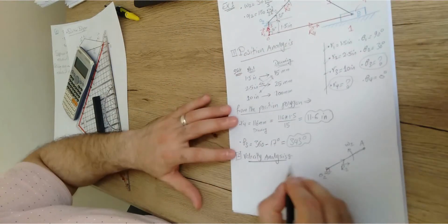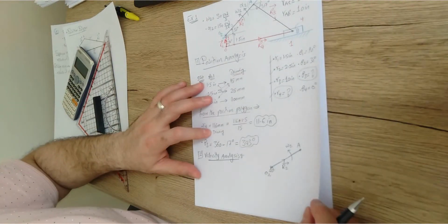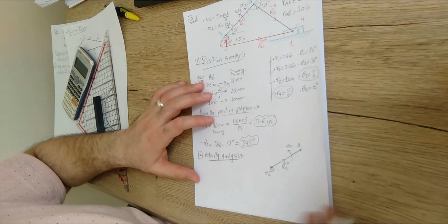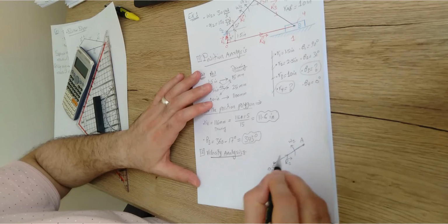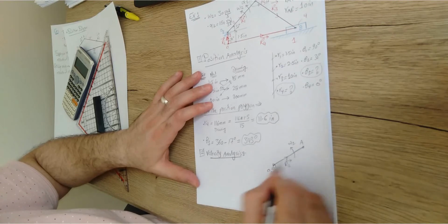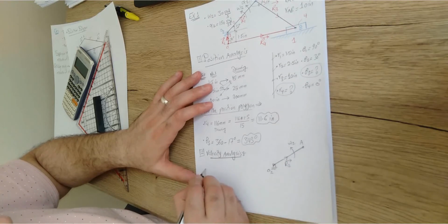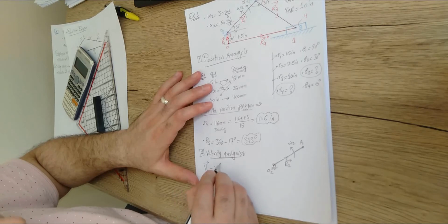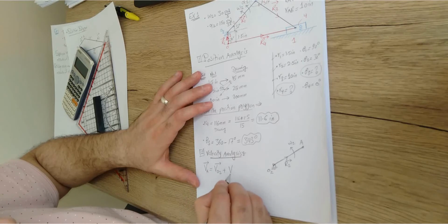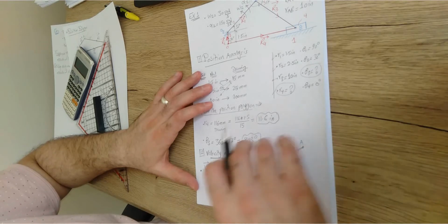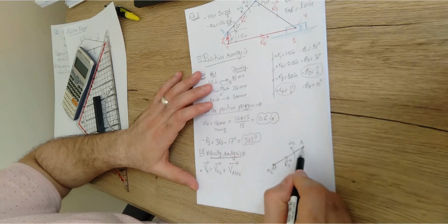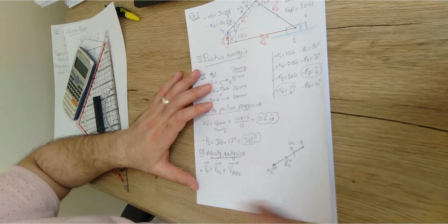Then your objective is to start writing the equation as we did in the dynamics class before for the velocity vector for this link, right? This is the first case, where we have a link that rotates about a fixed point. This link, again, is set up between two points. So we're going to say that the velocity of point A equals the velocity of point O2 vector plus the velocity of A relative to O2 vector. If you remember from the dynamics class, this is the equation that describes the relative velocity between these two points that define this link, right?